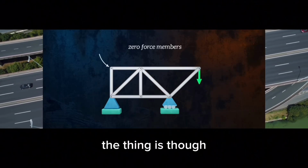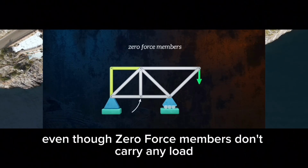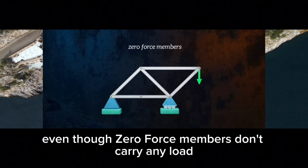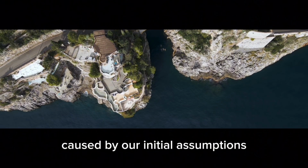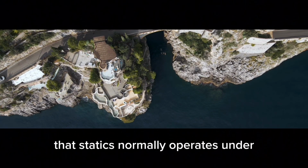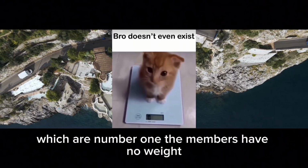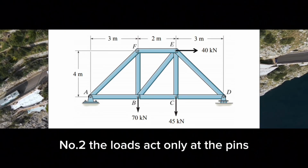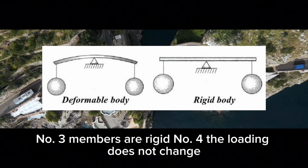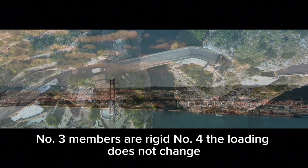The thing is though, we can make our bridge stronger with zero force members. Even though zero force members don't carry any load ideally, neglecting and removing them would be an error caused by our initial assumptions that statics normally operates under, which are: number 1, the members have no weight. Number 2, the loads act only at the pins. Number 3, members are rigid. Number 4, the loading does not change.